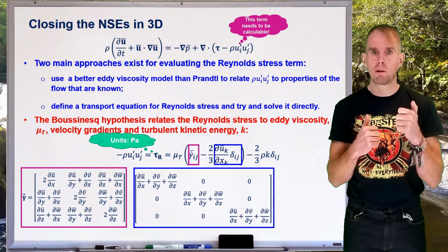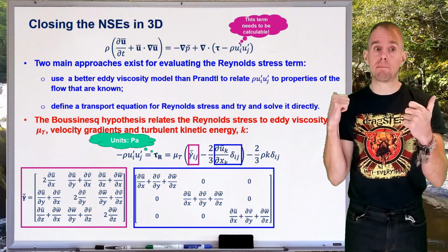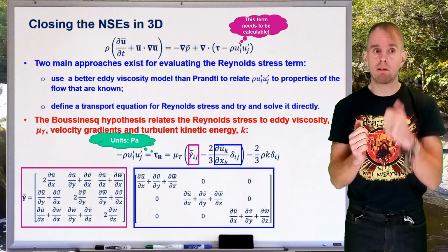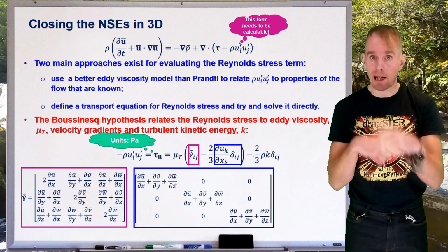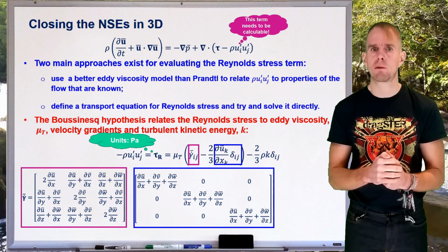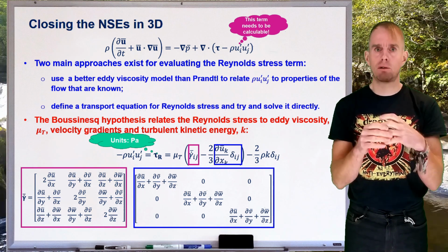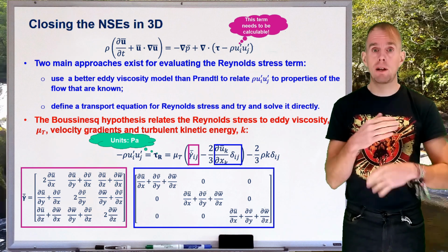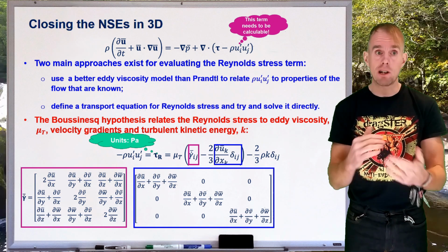When i equals 1 and j equals 1, that's the 1,1 position in our tensor, which is the top left-hand bit. If we go right by one unit, where we've got that 0, that's when i equals 1, j equals 2, and then we count up in k and form our continuity equation. But because 1 doesn't equal 2, delta ij equals 0. So if we think about this equivalence between the summation convention and for loops, then we hopefully have a way that we can calculate the contents of these tensors using summation convention.